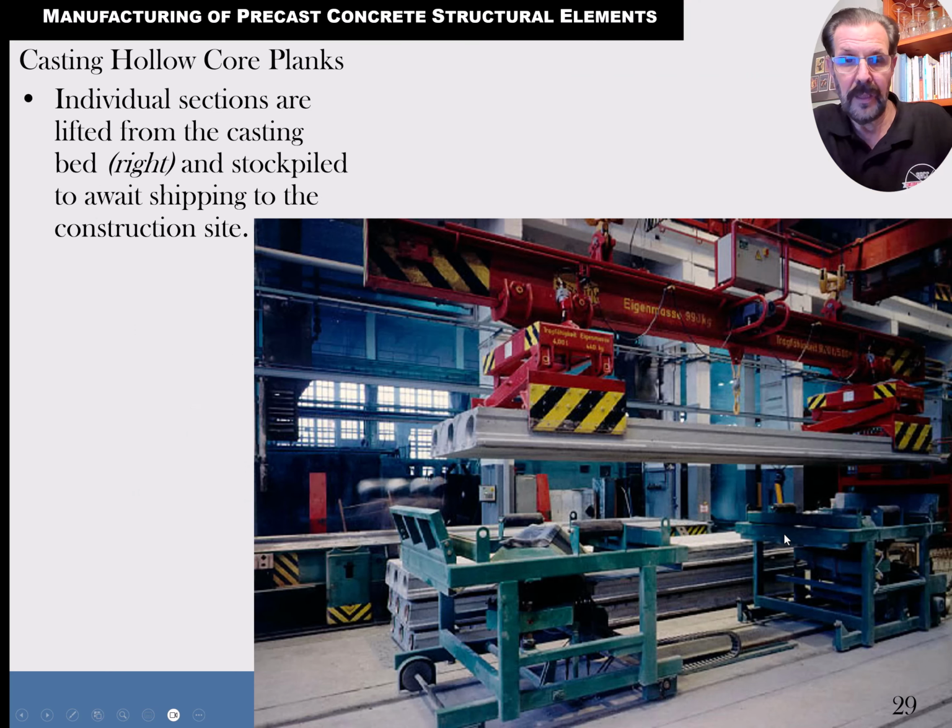Okay, let's see. Here they're picking up a hollow core slab, or in this case, they're calling it a plank. But it's with the big lifting clamps that grab it by the keyway. But that's not very practical when you're trying to place it right in its final resting place next to another hollow core slab, because you can't get it close enough. So they'll use either a vacuum pump or some very slender cables that they're kind of cradling it in. That's not the best, but the vacuum pump is the best.